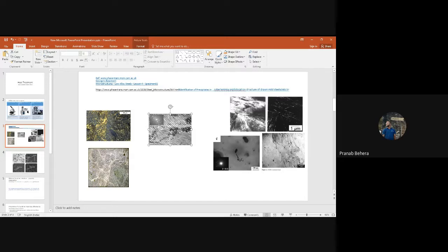Electron, magnification. Magnification, yeah, one part is magnification, but what is the important part? Just look here. Here the resolution is good, right? You can easily resolve one plate of ferrite and cementite, but it is very difficult to resolve here. You understood now? These are clearly visible. Yes, sir. They are very thin. Ferrite and cementite are very thin, and you can easily resolve them into individual plates.